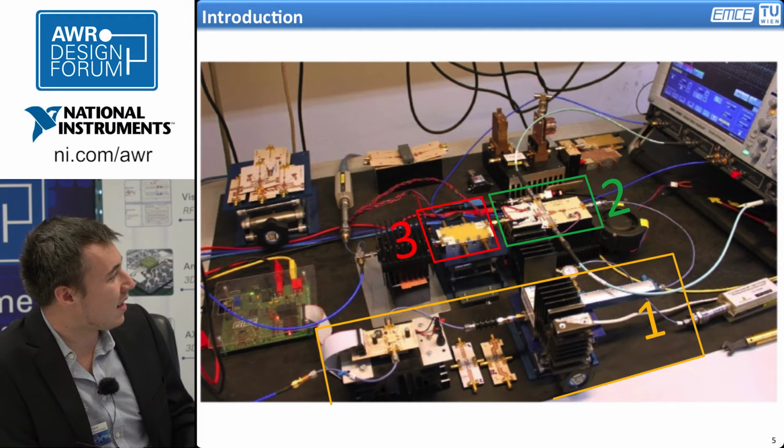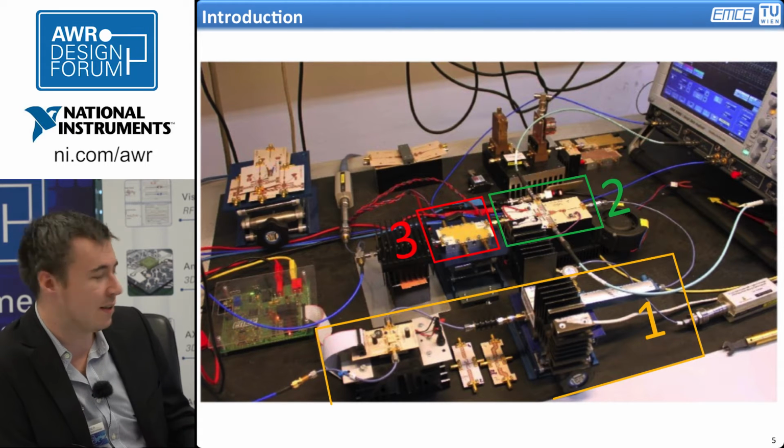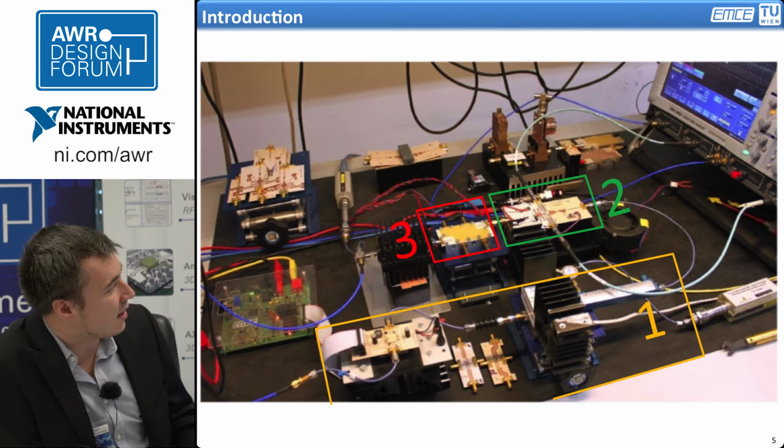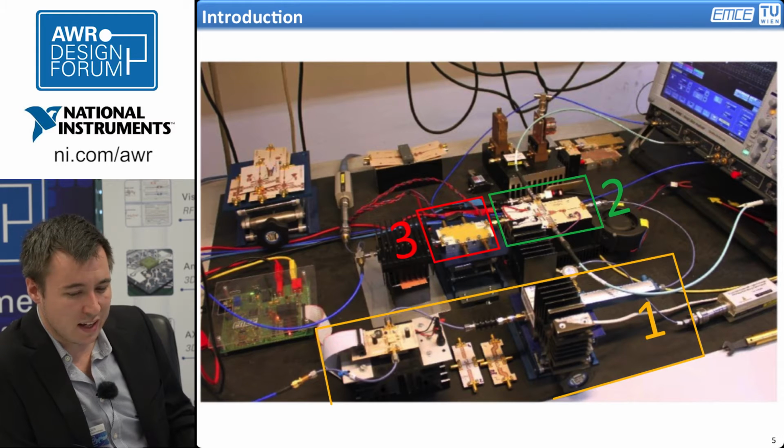Then the signal is supplied to the power amplification stage, which uses the 10 watt Cree HEMT device everybody uses for building this kind of amplifiers. And then here at the end you get a glimpse of the reconstruction filter and the matching network, where we already had the presentation today on how to build this kind of fancy matching networks.